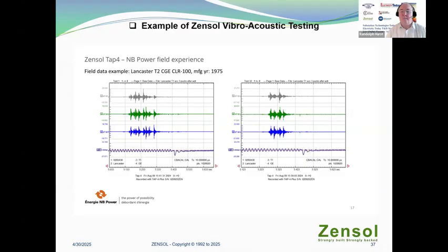We focus really on the motor current, because it gives a lot of information: when to start, when to stop, and the synchronization between the tap changer and the diverter, how the diverter works according to the motor current.